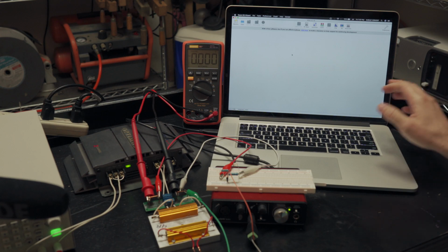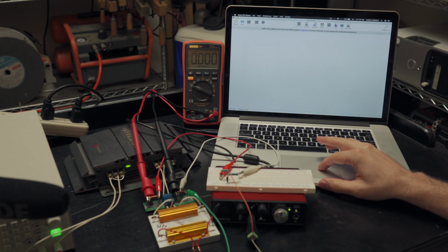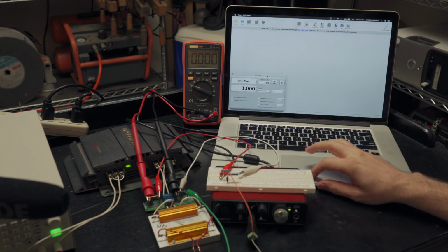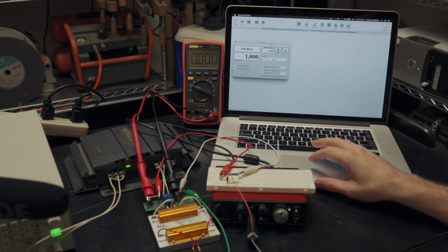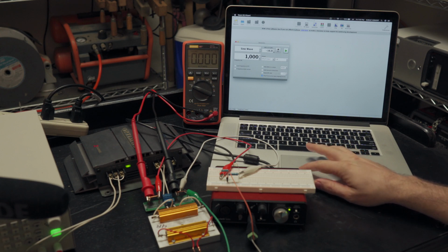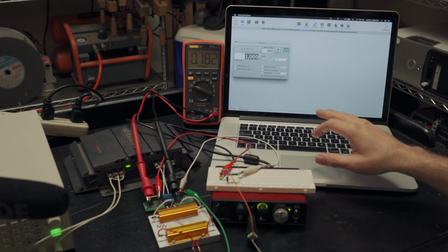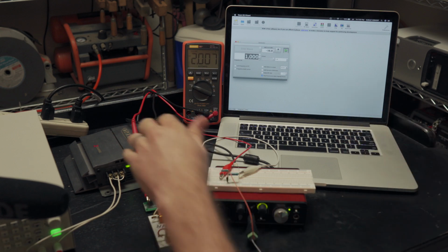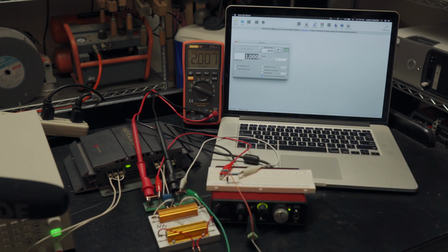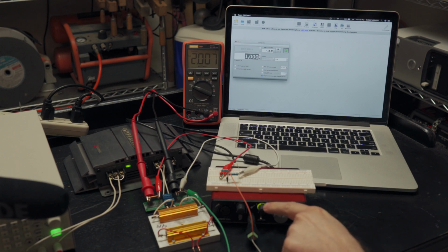And so the next thing to do is to pull up the generator. So here's our gen right here. And we can start generating a tone. And so I've got the multimeter hooked up here so we can see what our power level is that we're generating here. And I'm going to turn this right on down because I've already set this up to be a certain power level. So let's see. So there, negative 16 dB, we're at almost exactly 1 watt because once again, we're measuring into the 4 ohm load here. So we've got 2 volts RMS into our 4 ohm load, which is 1 watt output. And you can also see that our input indicator has lit up green to show that we have signal coming in.